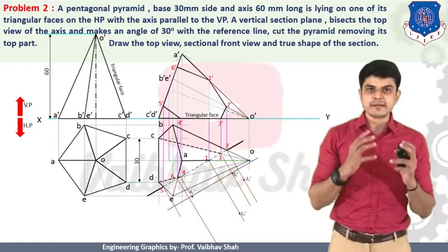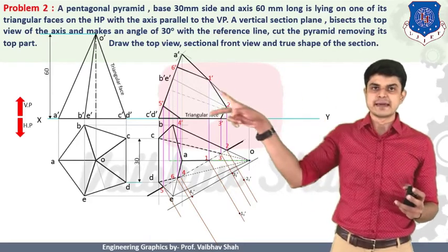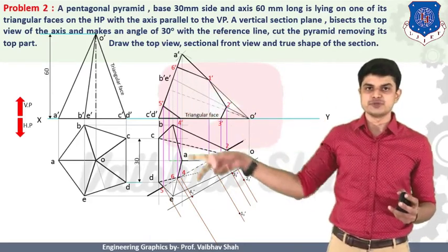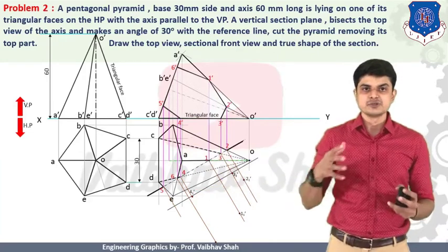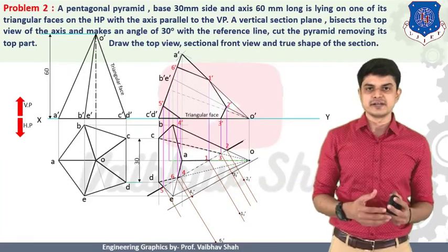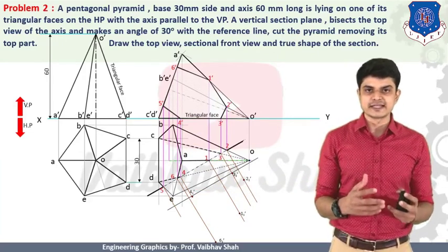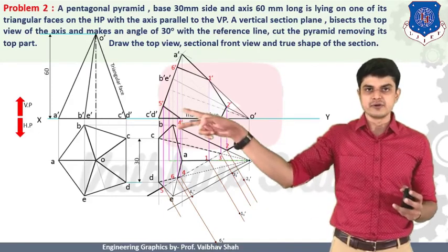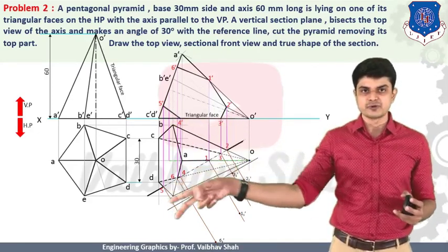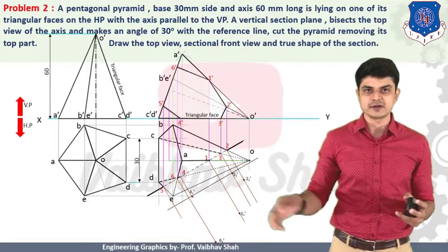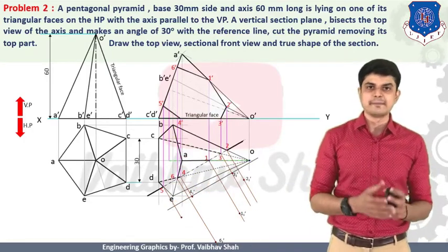Now let us plot point number 6 first. You should take the dimension of point number 6 from your xy line, and you should put point number 6 dimension here. So you will have a point 6 generated there. And thereafter finally you should take the dimension of point number 5 into your rounder from your xy line, and you should put your rounder on this inclined line, and you should plot this point. So you will have your final dimension generated.